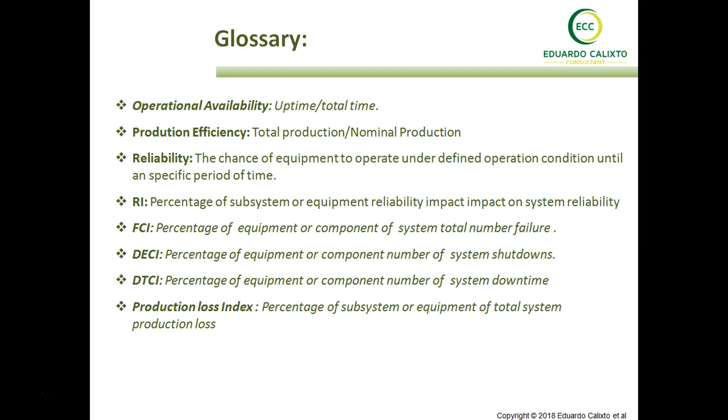Usually the accessibility time will be the same, and also the time to open, but in some cases you need to disassemble the whole equipment to change one component, while in others you just open the equipment and can remove some components. That's the variation in replacement. In the case of repair time, of course, you have even more difference, and that difference can cause differences in the performance of the downtime critical index and the down event critical index.